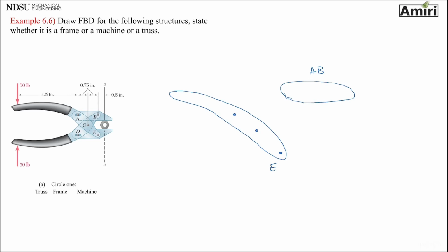AB is not a 2-force member. I don't think there is any 2-force member or 3-force member. They're all multi-force. Why not? Because the forces are not only towards the ends of it. There is one contact surface here. Let's call it whatever, Q. Right there. Point B is a pin, so I like to put a BX and BY on it. Point A is a slot, so it's like this. It can move in this direction, but it cannot move in the Y direction. So it only has a vertical force A. Okay, so that is my multi-force member.